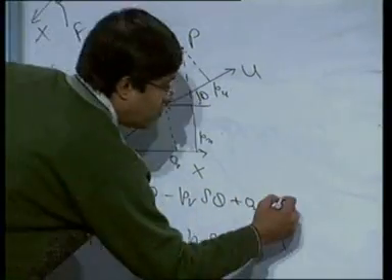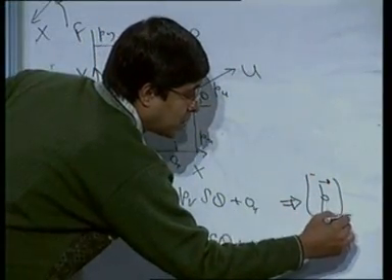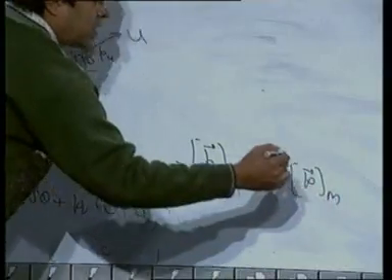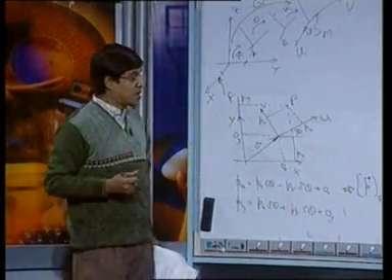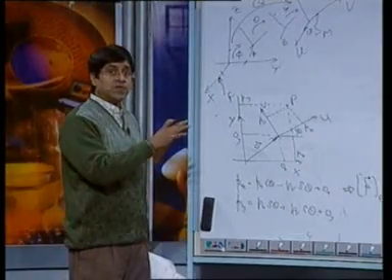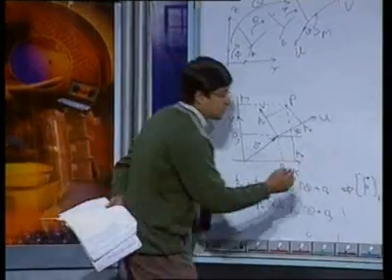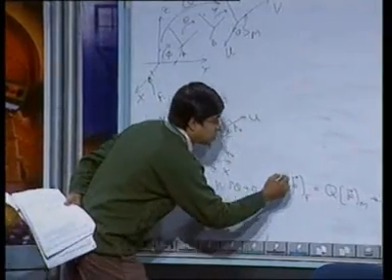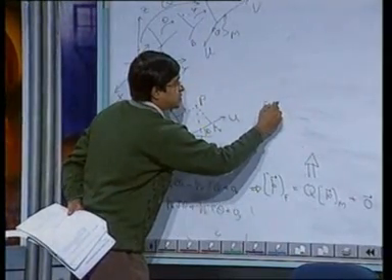Putting it in a vectorial form, one can write P represented in the fixed frame is equal to Q times P in the moving frame, plus a shifting. But this is no longer only a matrix transformation; it is added by some vector. If we want to program it, and for unified operations, there is a way that we can consider it only as matrix multiplication. How is it? It is as follows. Now, let us go from here and do certain tricks here.